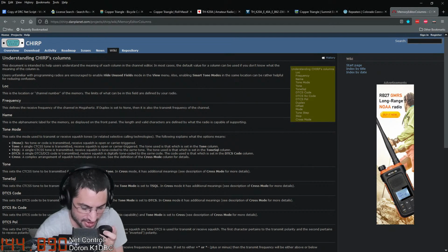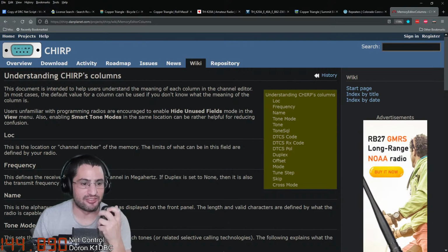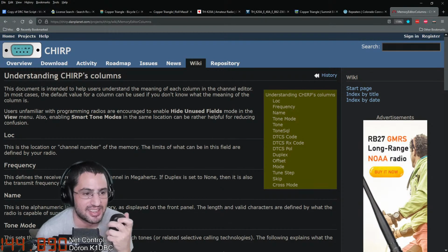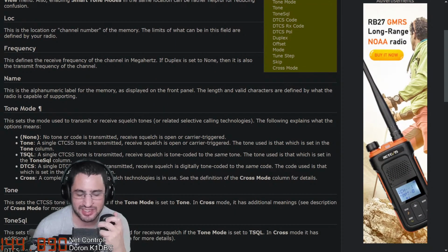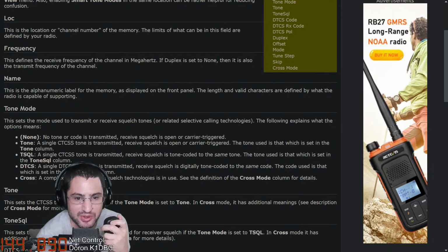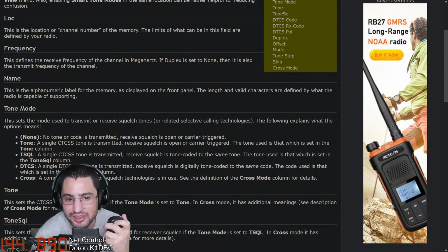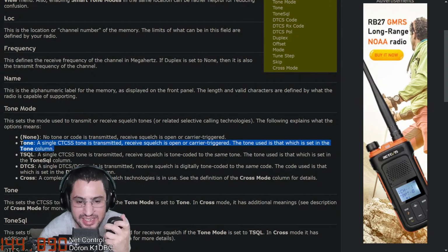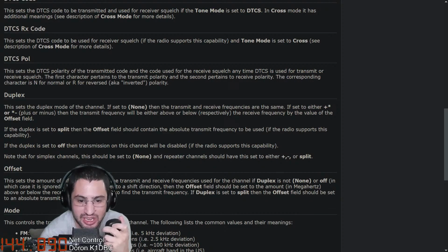All right, KG5PDF. This is K1DBC. Yeah, good information there. If you can program things in ahead, that makes your life a lot easier. The basics of a repeater that you would need to put in would be the receive frequency, the transmit frequency, and any tone that you would need on it, and again, the duplex or offset.